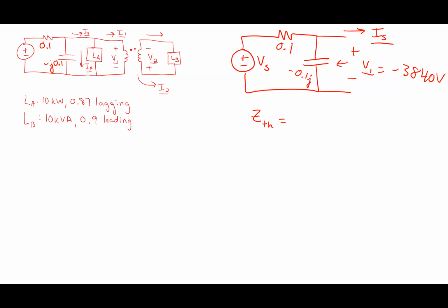So the Thevenin equivalent is basically from the perspective of a current that's flowing into those terminals and then splitting. This is the most important stuff, because when you get into electronics one, they're not going to ask you P and Q. If you're electrical and you take 3142 with me, you'll have to do that. But that's two semesters away. Next semester, you need to know circuits, so make sure you're ready for that stuff. So Z Thevenin would be 0.1 in parallel with negative J 0.1.